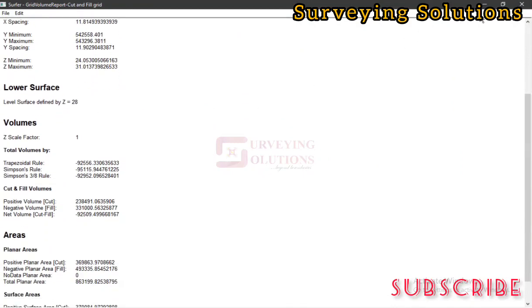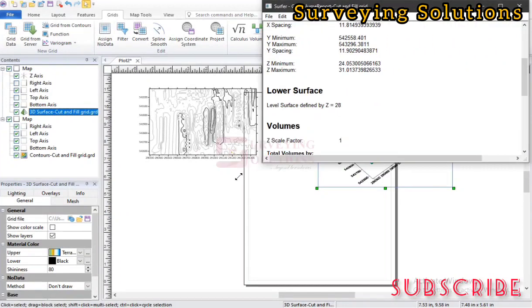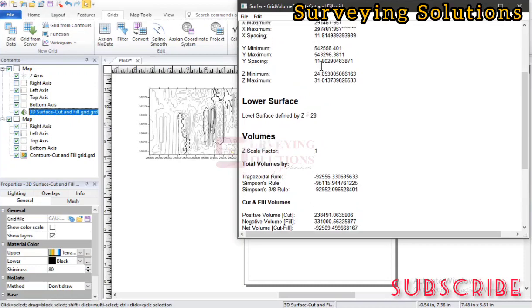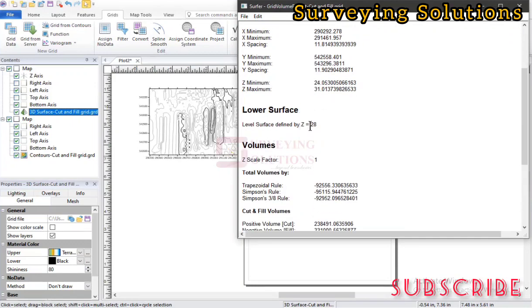Now from our report, it is obvious that, okay, I wouldn't want it to be over the screen like that. Good. From our report, we can see that the minimum Z value for the default data, or the first surface, is 24. The maximum is 31, right? And our lower surface is 28, which means we are going to fill up 24 to 28, and then we are going to cut 31 to 28, right?